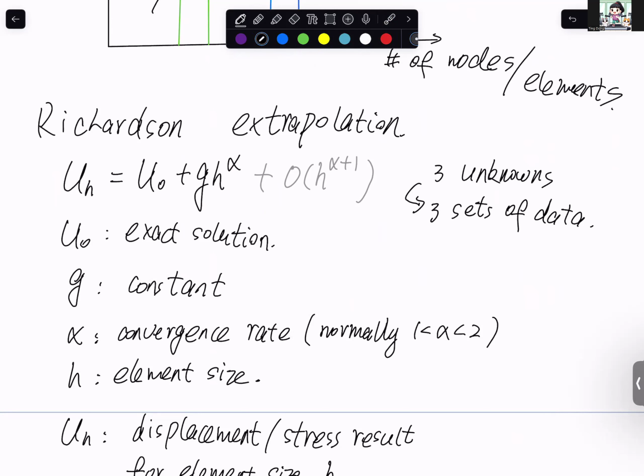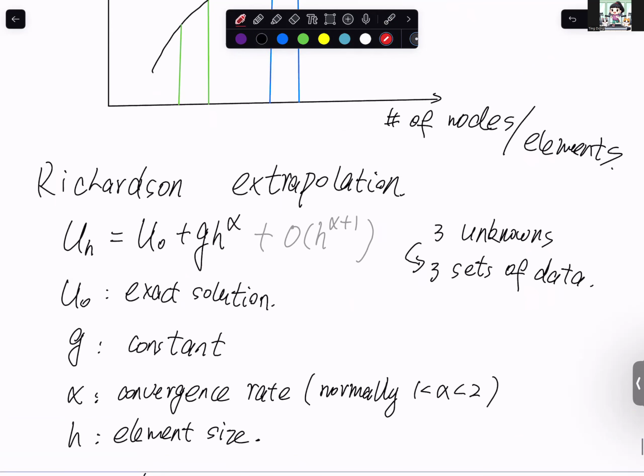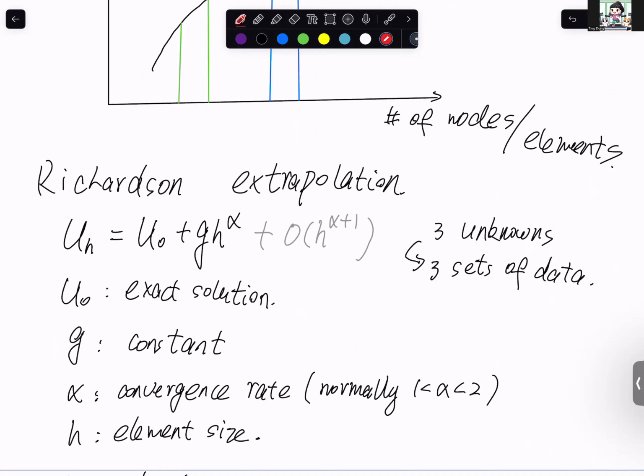Another thing I want to emphasize here: if you have a truss problem, like a truss structure, that probably should be fine, because a truss member is tension-compression. Each truss you have 1 element, you should be fine. Increasing the number of elements does not really change the results, because tension-compression itself is already accurate. You use 1 element, you use 10 elements, it's always sigma equals F over A.